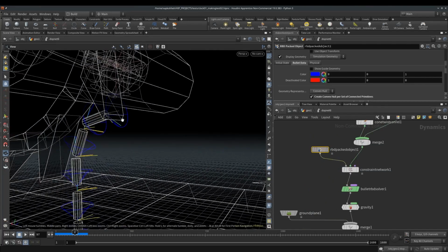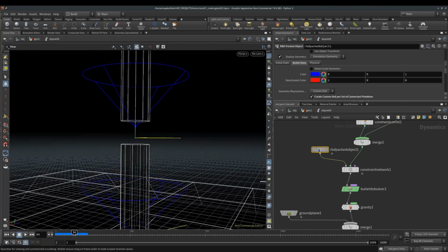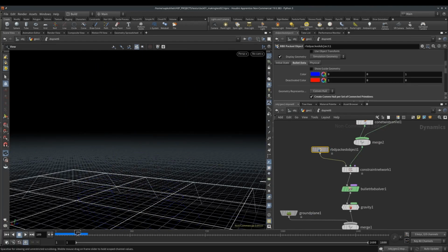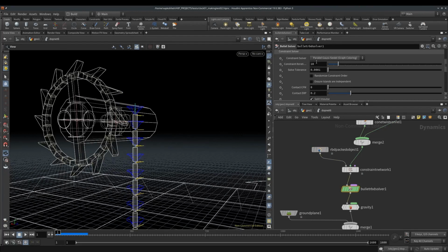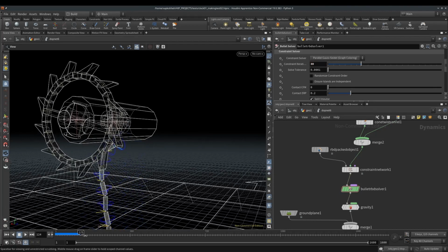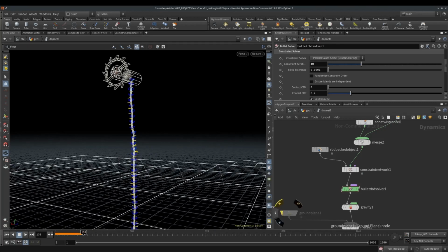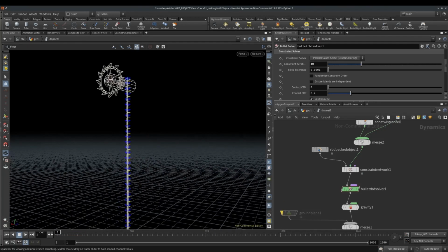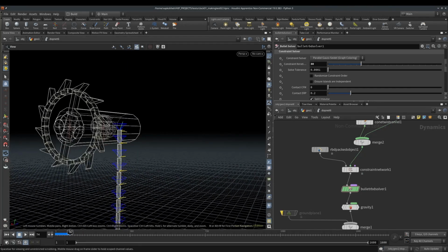What you will notice is that right now this rope is undersolved. You see the constraints are stretching out, and since we're doing a pretty stable thing, we can just go here and increase the constraint iterations, and everything should just work better, not exploding. And that's what seems to be happening. Don't need the ground anymore, since the rope will be just hanging there.